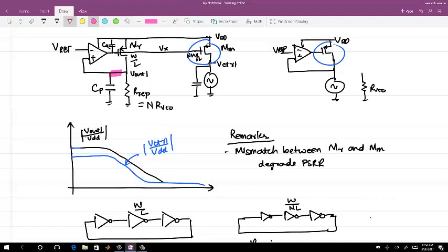Let me put it this way. The capacitor at V control, you will put not for regulation or anything right now. You are going to put it basically for suppressing any ripples you are seeing there. I mean the regulation has already been done. So if the VCO scaling factor is going by n, then the capacitor scaling should also go by n.